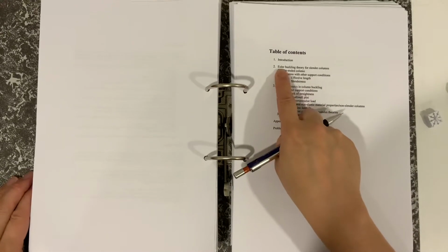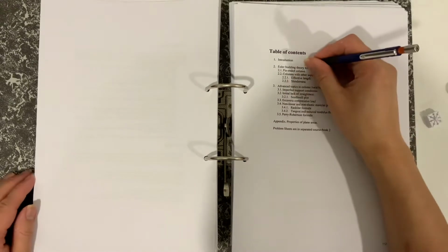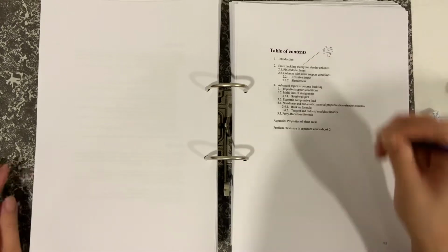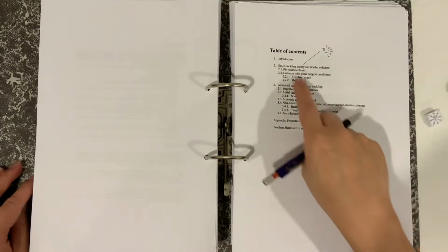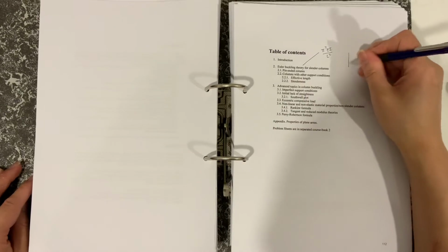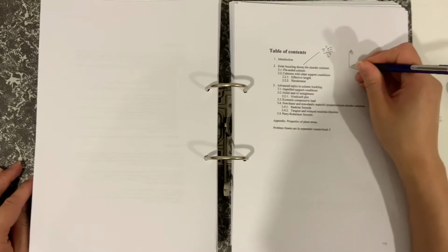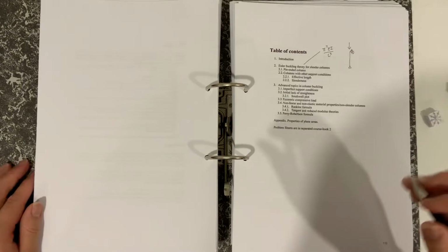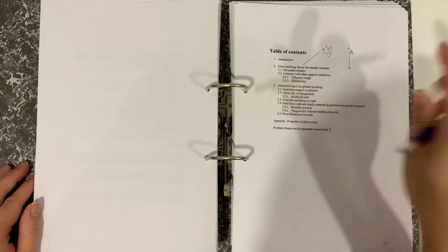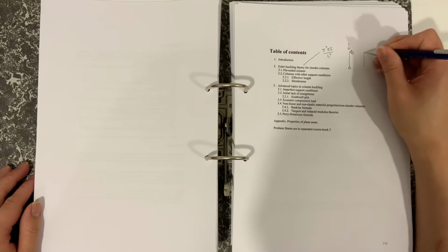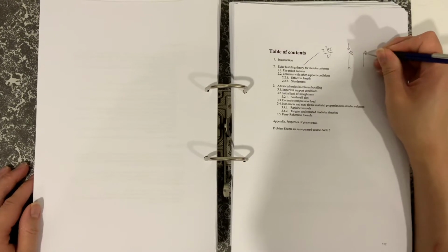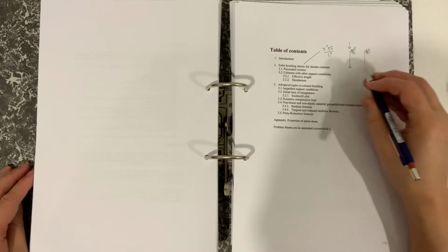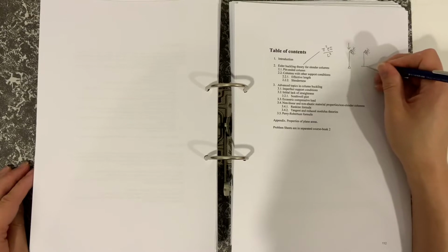So Euler buckling is going to lead us to pi squared EI over L squared for pin-ended columns, which is the one that I've just shown. The pin-ended column would be looking like that, with the load coming down like that. And then what happens when we change the boundary conditions? How do we handle it as engineers if the boundary condition becomes fixed?